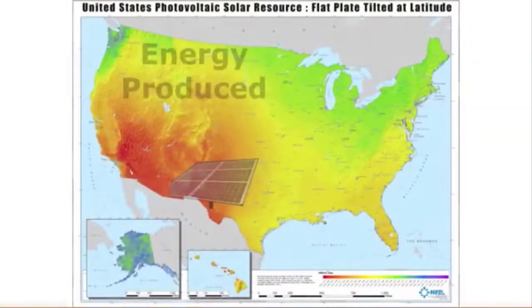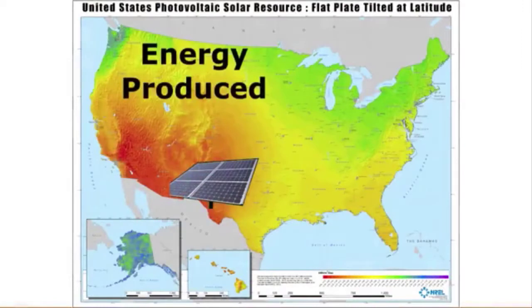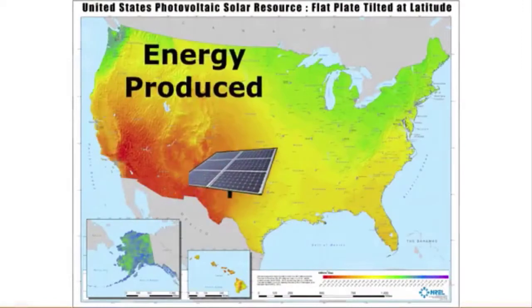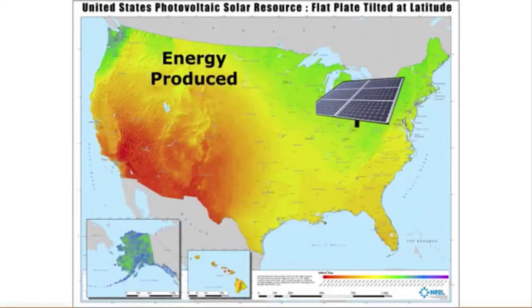Photovoltaic modules are rated by power, and that value is the power output under standard test conditions. As we discussed previously, that corresponds to a sunlight intensity of 1,000 watts per square meter at 25 degrees Celsius. This means that a PV module in a sunny place with lots of daylight hours produces more annual energy than the same panel in a less sunny location. So more sunlight power multiplied by a specific amount of time means more solar energy and solar electricity.